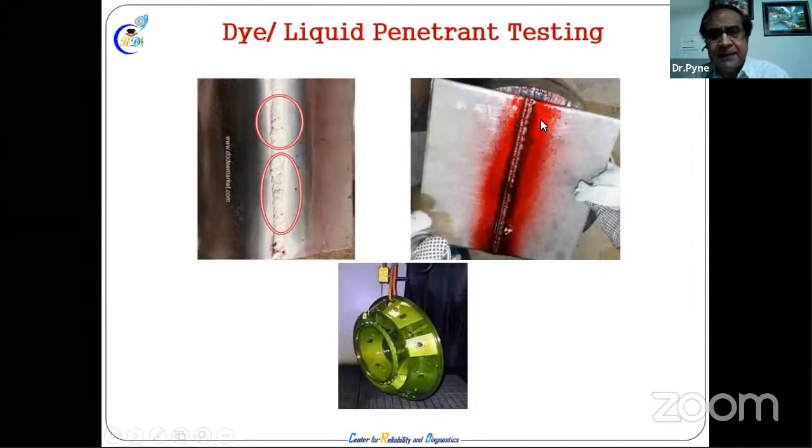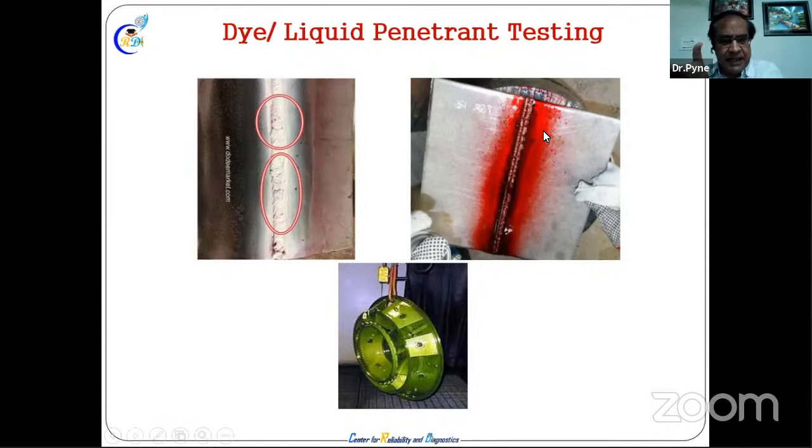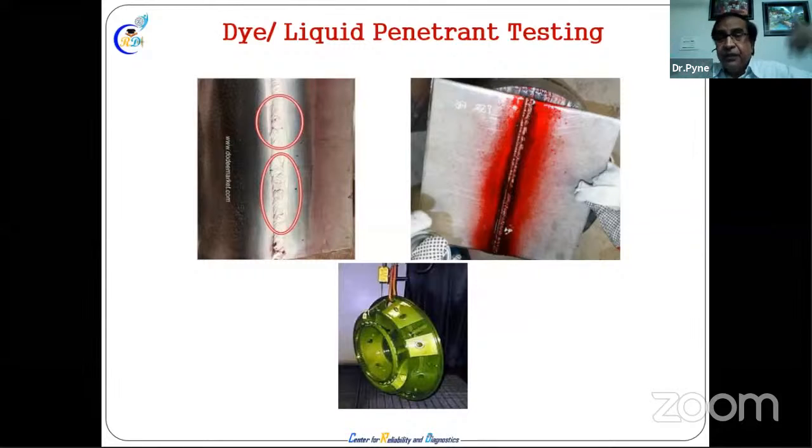Take any part, say a furnace shell. The temperature should be below 25-30, or maybe 60 or 70 degrees centigrade, but in certain places we are getting 300 degrees centigrade on the outside, with 1400-1500 inside an electric arc furnace of the steel plant. So that much temperature is expected, but in certain places you are getting more. That means energy is going out, and there may also be a hole afterwards.